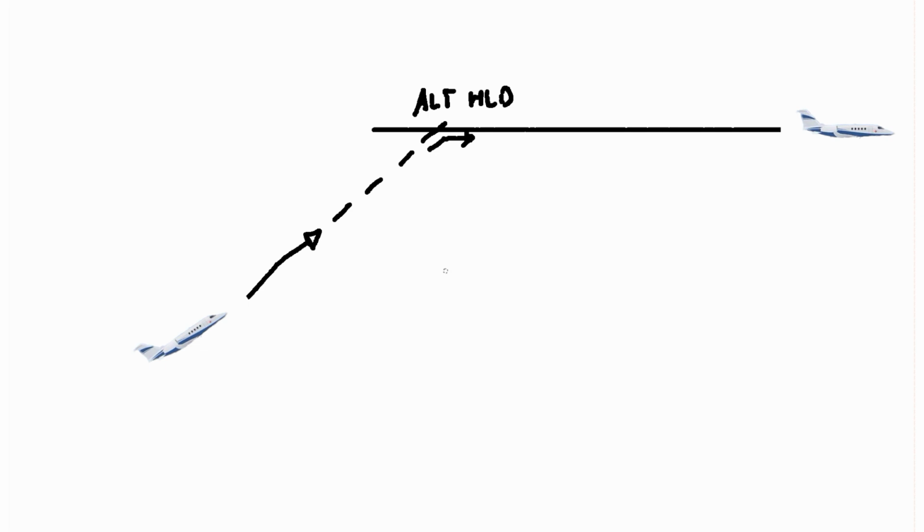Okay, how does this function work? Well, it's very simple. It measures the rate of climb of the aircraft once we are approaching the altitude. So you see, I could have a very shallow rate of climb, or I could have a very steep rate of climb. And basically what we do is draw a circle. So you can imagine that the system is drawing an arc of a circle that goes from the current rate of climb to 0.